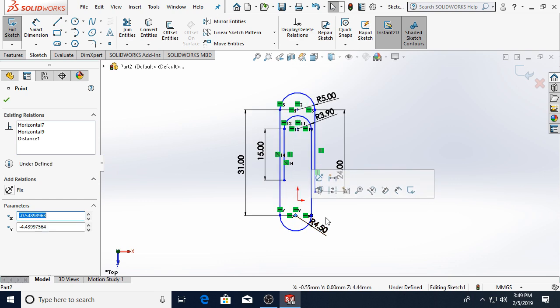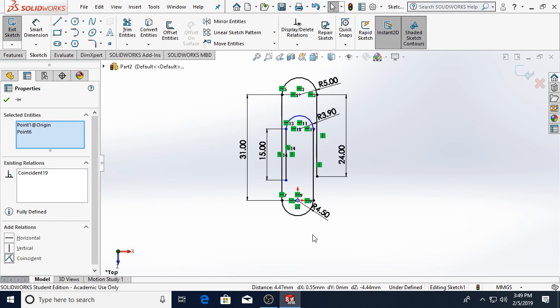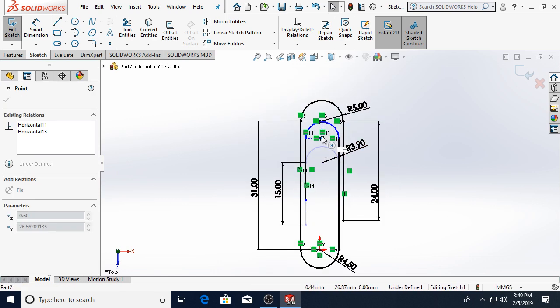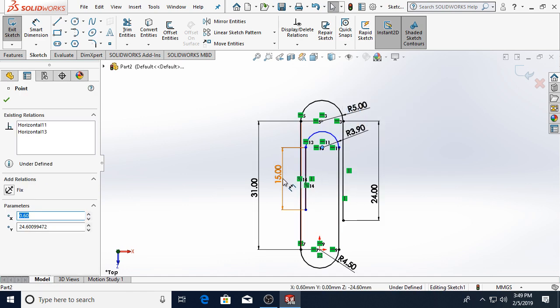So what do you say? Make the origin in the center circle? See, it works for me. Now I have 2 blue parts left, this top section of the inside part of the paperclip and the bottom part of this left line. Both of those will be constrained if I establish a position of this circle because the length will constrain this